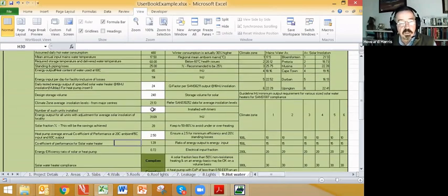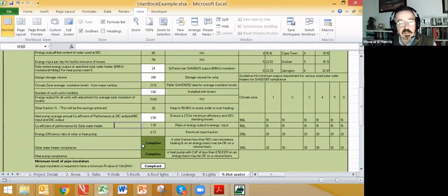So the comforting compliance message appears if we have our volumes correct, if we have sufficient heating power, or on the other hand, if we have a sufficiently low COP supplied by our heat pump supplier. And please do not hold back on consulting with either Graham or myself on the subject of hot water, because in many instances of heat pumps supplied, there's insufficient heating capacity and people are disappointed.